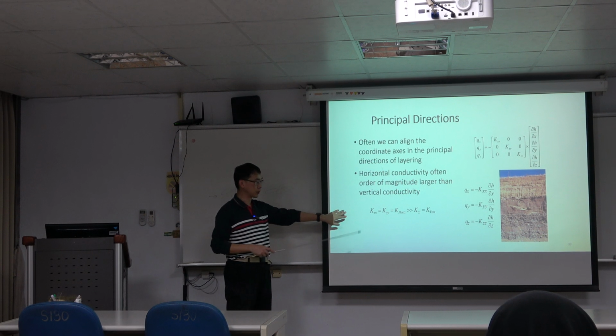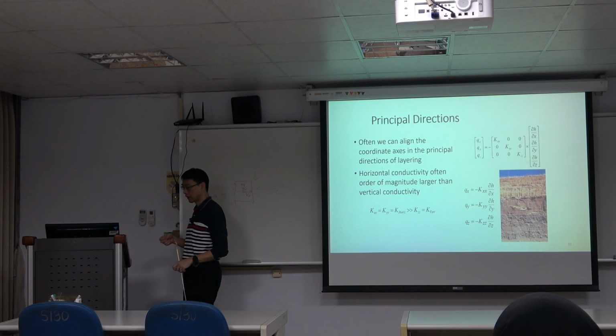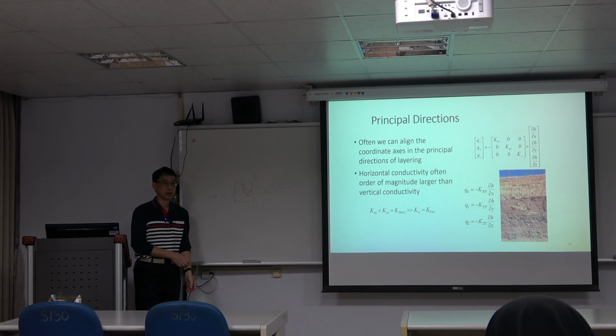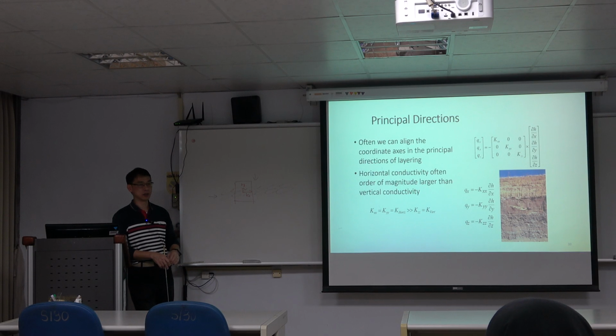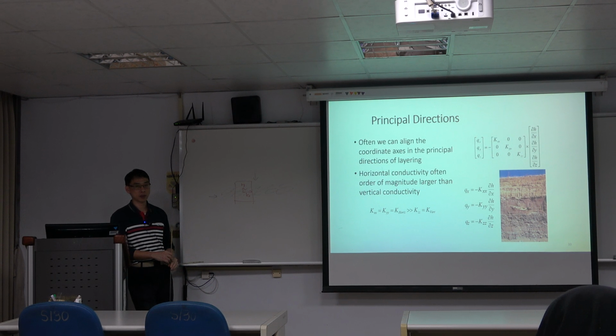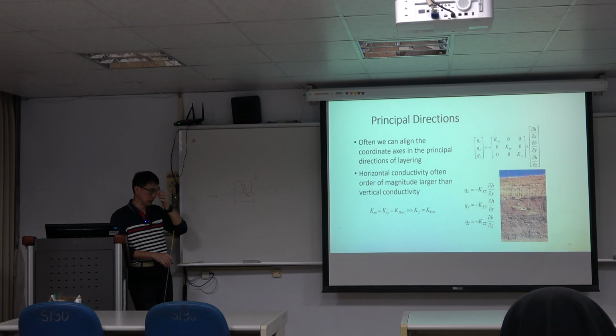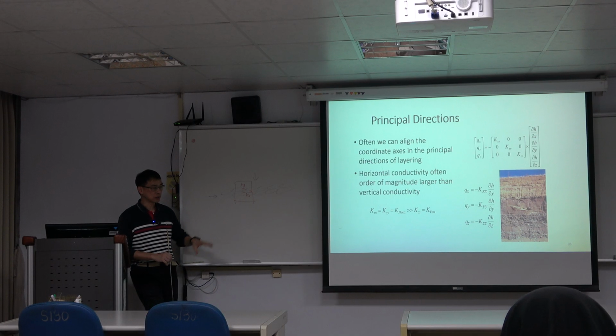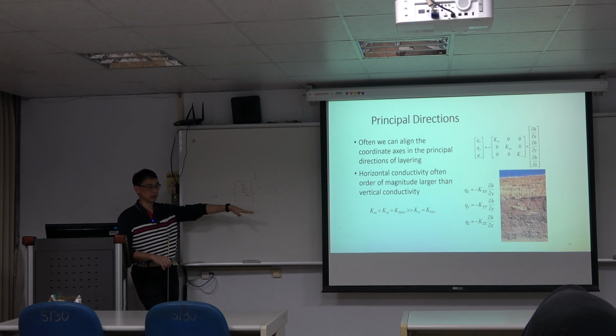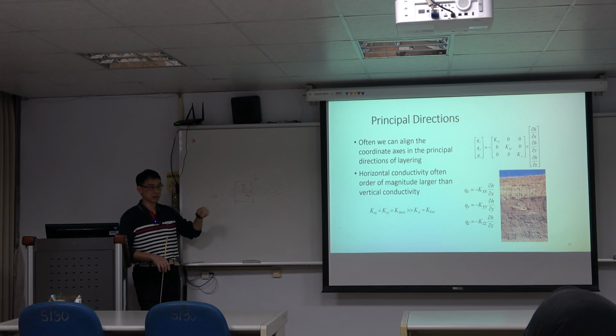But honestly speaking, because we mentioned that the K values or hydraulic properties themselves embed huge uncertainty, we do not care about the tiny or small differences. We just have approximate quantities, and then we can use that to quantify how much water volume we obtain. That's for groundwater resources. Most groundwater hydrologists have this kind of concept: the uncertainty itself is much larger than the differences between Kx and Ky. So you don't need to care about the tiniest differences.